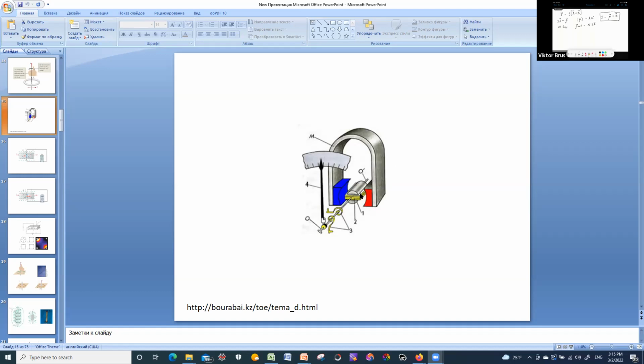So the external electrical circuit is connected to this current loop. The resistance of this current loop should be very small. We don't want the resistance of the amperemeter as a measuring instrument to influence the current in the electric circuit. So we just want to measure it, but not to affect it.